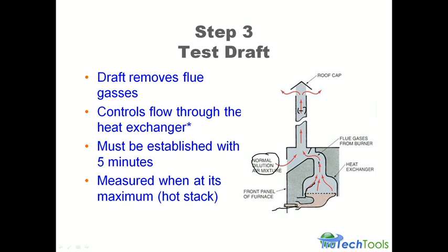And in here, in the heat exchanger, the top of this is actually positive pressure, because you're pulling in that hot flue gas and that burner's burning, you're forcing gases in there, you're building a positive pressure, and the pressure should flow from positive to negative, right, and go right up the chimney, okay? But the appliance, the draft, is engineered so it doesn't suck the flue gases out of the chimney. It dilutes, it doesn't suck them out. They naturally flow out, and the chimney is the area of lowest pressure, and it flows up and out the chimney. And in the process also it pulls in enough dilution air that it keeps it from condensing.